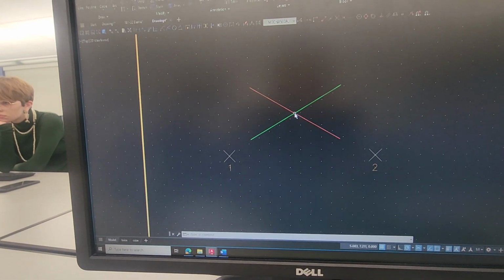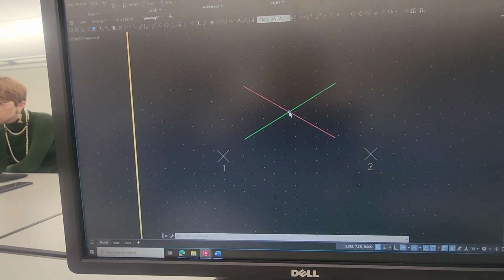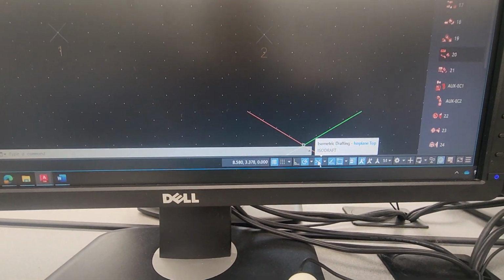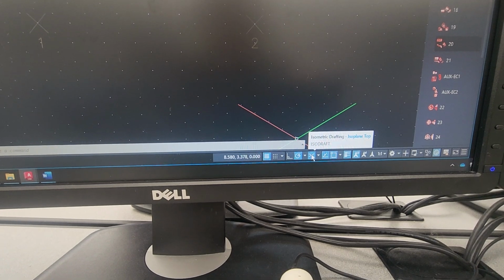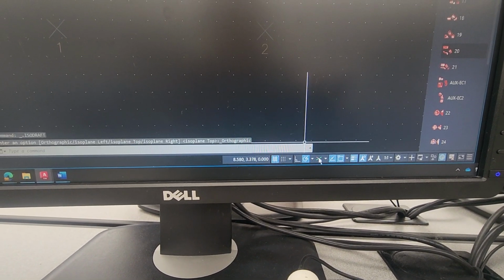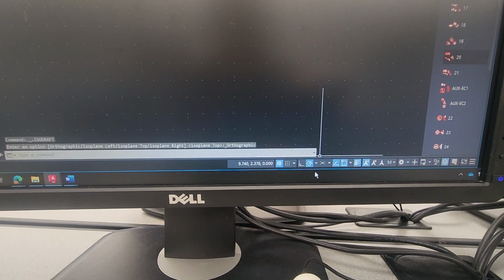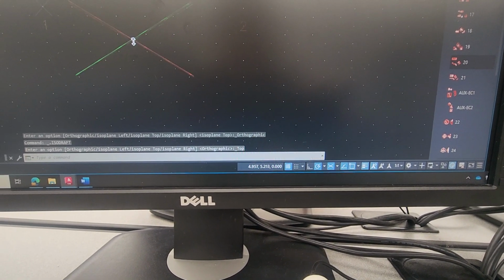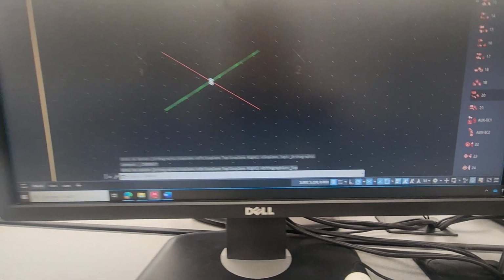See how this cursor is oriented right now? All right, what you can see is down here, there's a blue button. See that little blue button right there? It says ISO draft, okay? It's set to the top plane now. If I click it, it changes orientation. Well, it turned it off, I'm sorry, I don't want to do that. Hit that on. The F5 key you have on your keyboard will change its orientation.